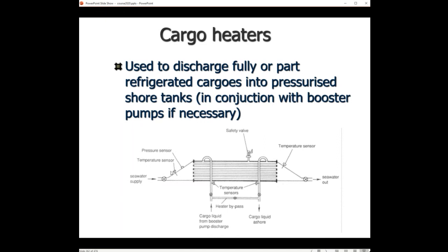That is why we need to know the seawater temperature at the inlet, and we need to know the seawater temperature at the outlet, because what might happen, don't forget that we send here cargo with negative temperature. If the capacity of the seawater is insufficient, we might risk that by the end, when the seawater is leaving the heater, the seawater gets frozen. That is the highest risk of this instrument.